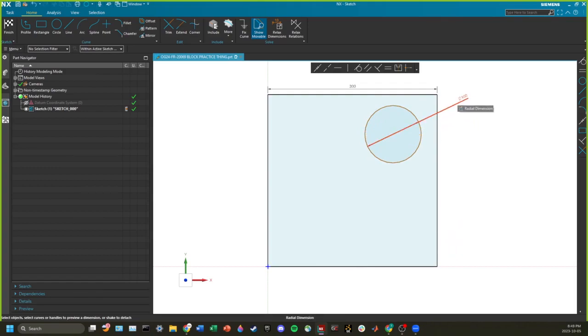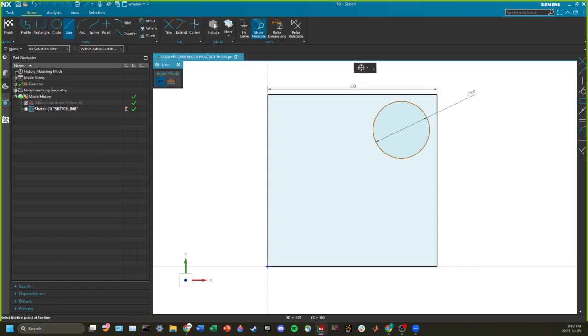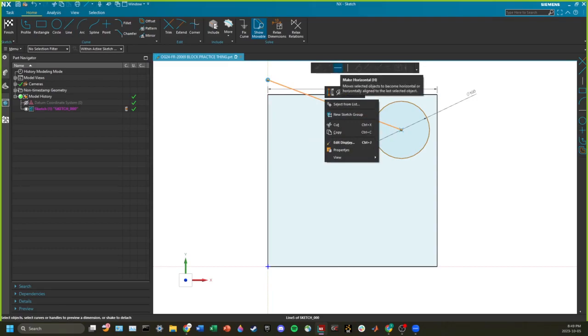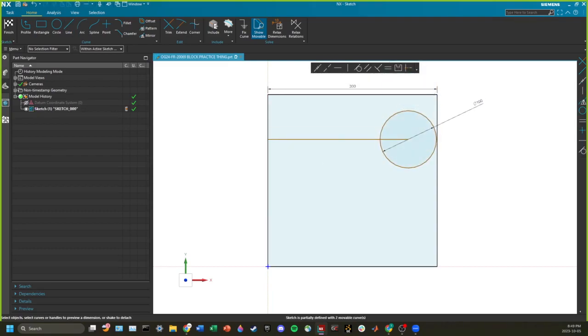Something that I really should have put in the tutorial video, last week's meeting, was how to make construction lines. So how do I define this guy? It's just kind of floating out here. One way I could do it, I could click it and select something to base it off of. Another way, which might be better visually, is if I click with a line, I'll just draw out here. I'll make this guy horizontal. There we go. I'll draw another one.